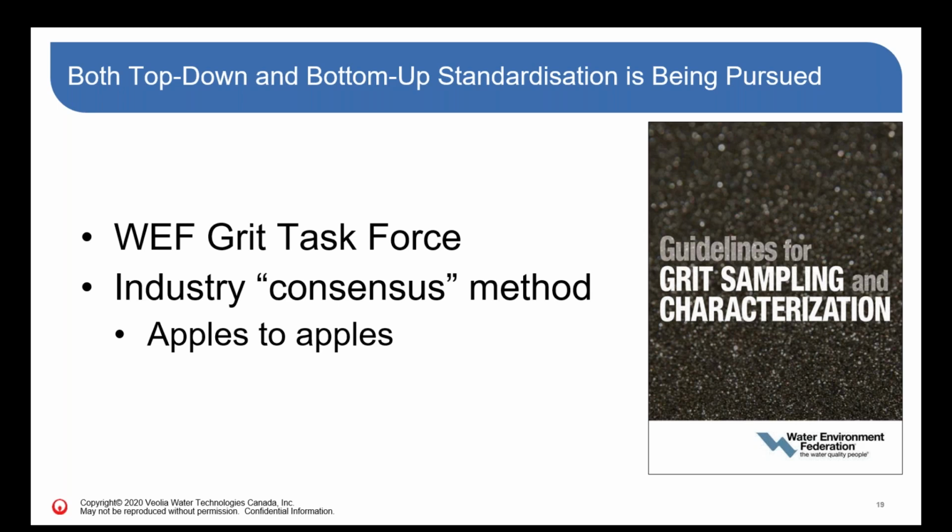Also looking at this from a bottom-up perspective, the industry is increasingly coming to some kind of consensus around how the test should be done. That industry being folks like Veolia, who manufacture these systems, and consulting engineers, for example, who are specifying these test methods as part of tender documents. Broadly speaking, that standard method that's becoming a consensus in the industry is the wet sieving, then the sand equivalent size settling method, and then the dry sieving. And that's the method that Veolia uses whenever we're providing a guarantee on our grit removal systems.